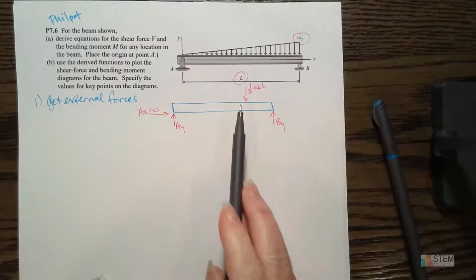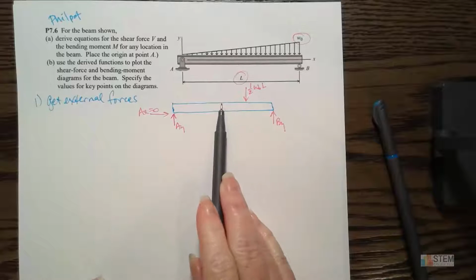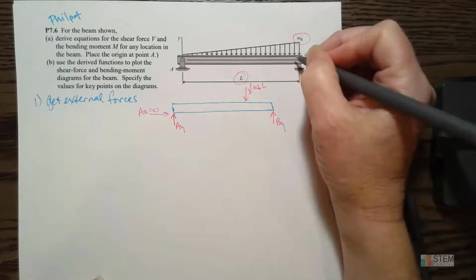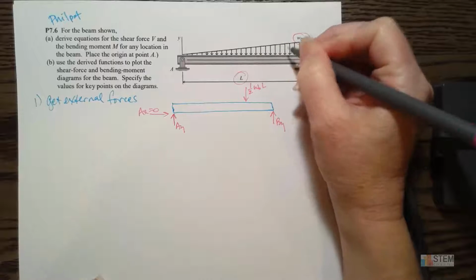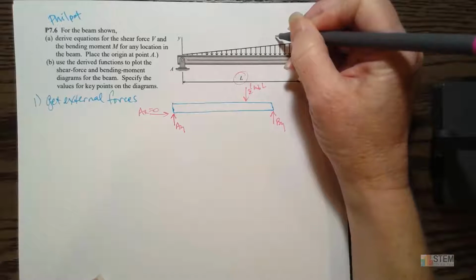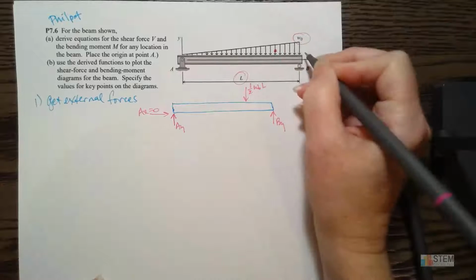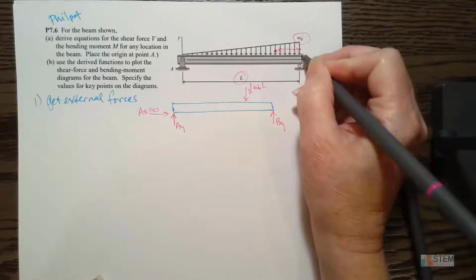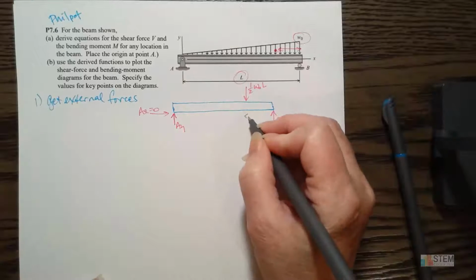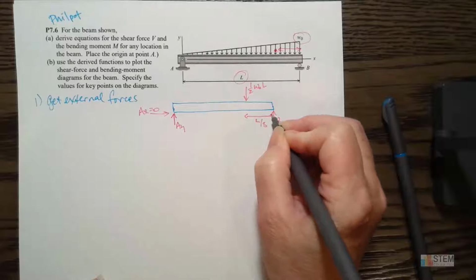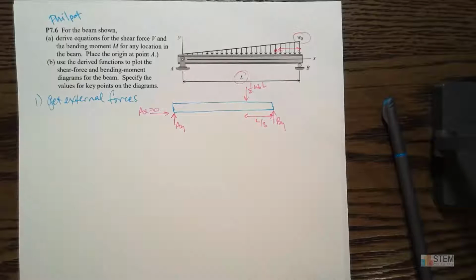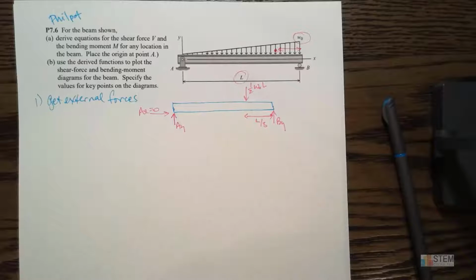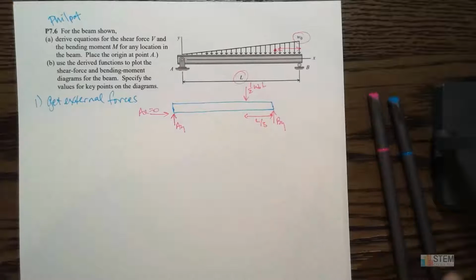And then we need to know where to place it on the beam. Notice I didn't put it in the middle. And that's because since this is triangular, we need to have the resultant force acting through the centroid of the triangular region. So if y'all remember, centroid of a triangle is basically 1/3 of the length from this bigger side over here. Right, so that's where we're going to be. So this will be L/3, just from the location of a centroid of a triangle. All right, so now that we've got this established, we can go ahead and solve for AY and BY.